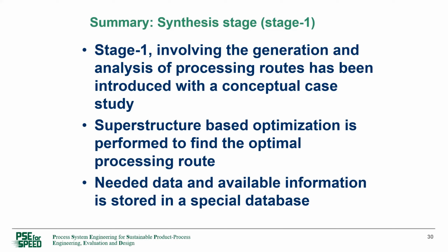In our case, the models are simple mass balance. So unless there is a recycle back, the model equations are linear. And then we solve that mass balance, and then we add the temperature and pressure data so we can do the energy balance, and we can then go forward with it. So with that, I will end, and if there are questions, I will take the questions.